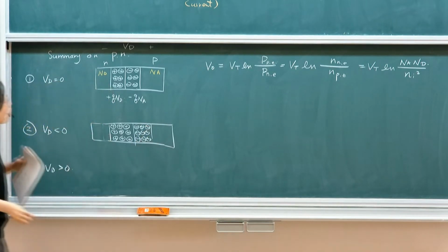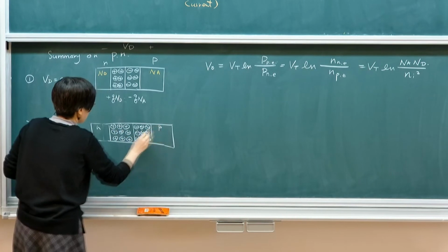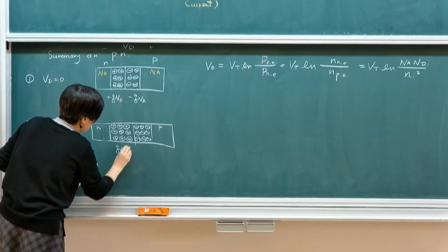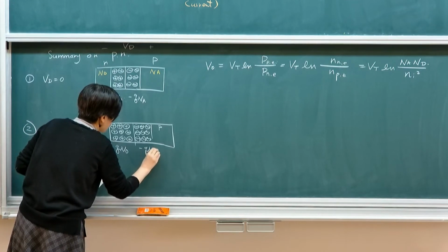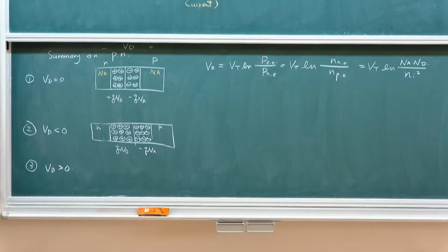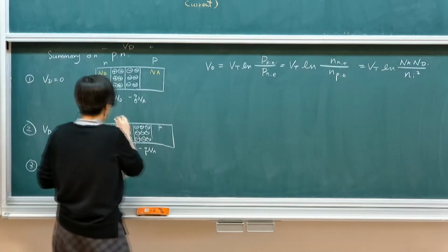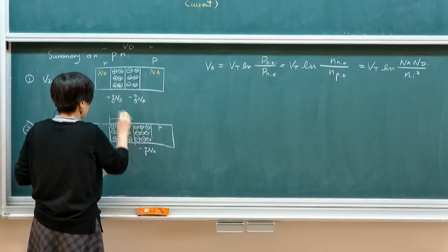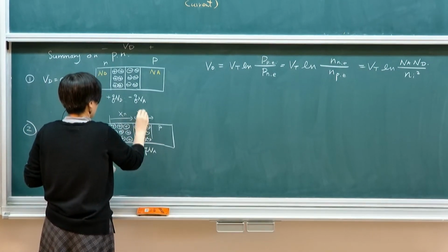Okay, you see a widened depletion, and this is still QNA, and the doping concentration or the density does not change. But one of the key things I want to mention, which is true for any condition, is that there's a depletion width, Xn, Xp.